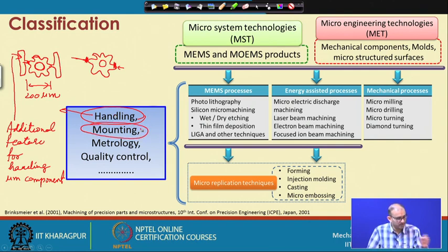Now, coming to mounting. So, handling is done. Now, how to locate the location where it is being assembled? At that time you need some type of reference surfaces. Those reference surfaces you have to create here, suppose these are the 4 points. So, you have to align with respect to these 4 points, and then robotic assembly also comes, or some type of pneumatic gripper will come. It will hold this particular gear by vacuum and then place it, and then the vacuum will be switched off.